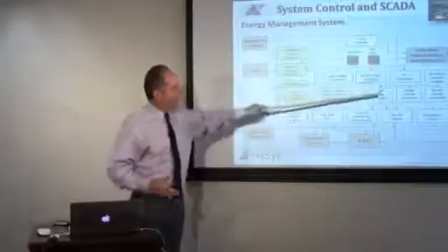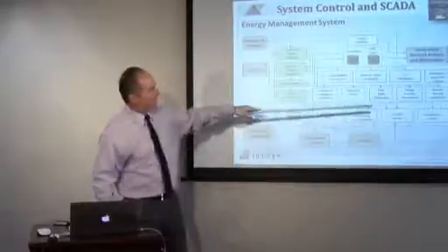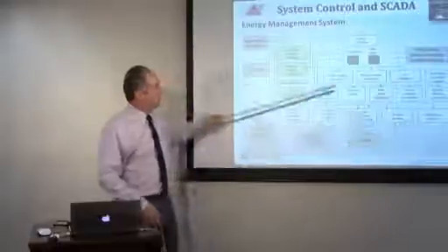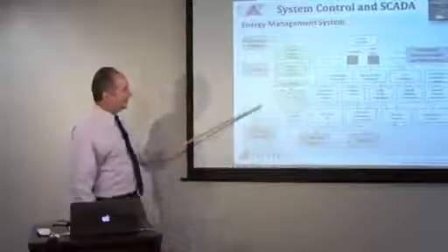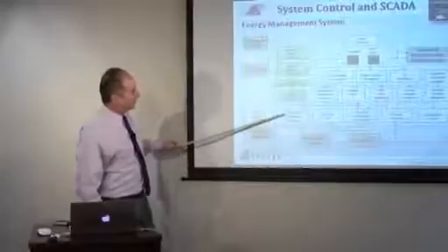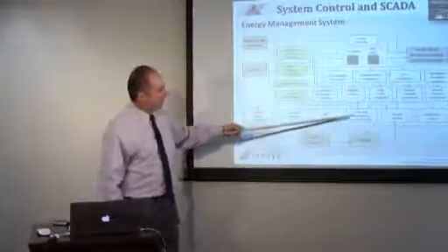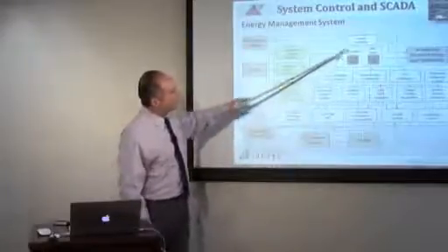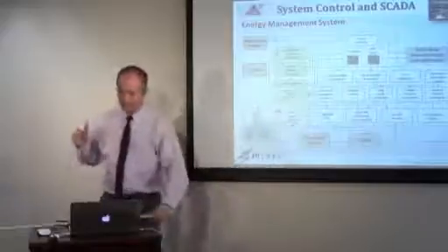The energy management system fault calculation calculates fault currents if something were to happen. Voltage security assessment looks at the stability of voltage. There's also reactive power scheduling, and then contingency selection and analysis, real-time optimal power flows, and real-time contingency and constrained optimal power flows. When you look at the different programs and operations going on in the background to help an operator,